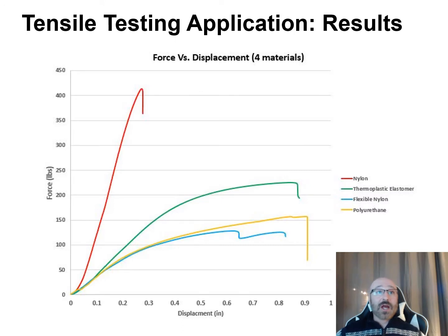So this right here, I left in force and displacement. For my application, I was more concerned about the max load that each of these types of materials is going to be able to withstand before we see failure, and which one's going to stretch, and is stretching too much for this application.